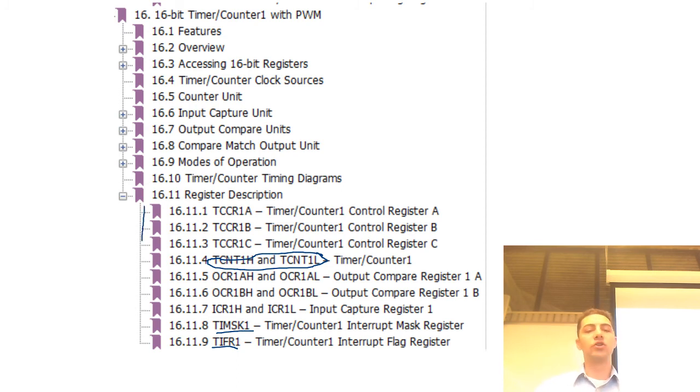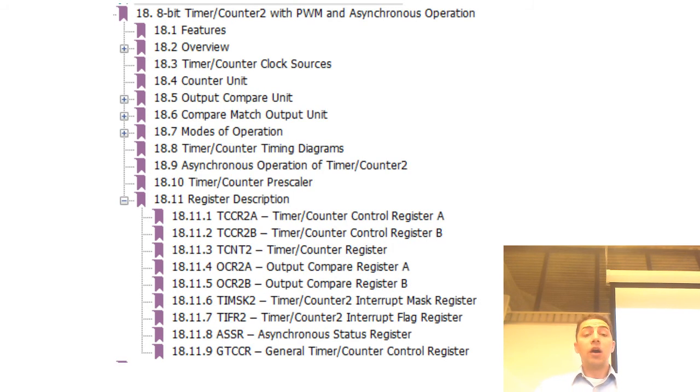And we've got some more control registers. We do have an input capture register, but I don't think I've mentioned it once, have I? Except in one context where it is the top value of CTC mode. We'll get to that in a second, but we're not going to talk about input capture or measuring pulse widths here. Oh, look, timer 2. We've got some control registers, our free running count and output compare, and the timer interrupt mask register.